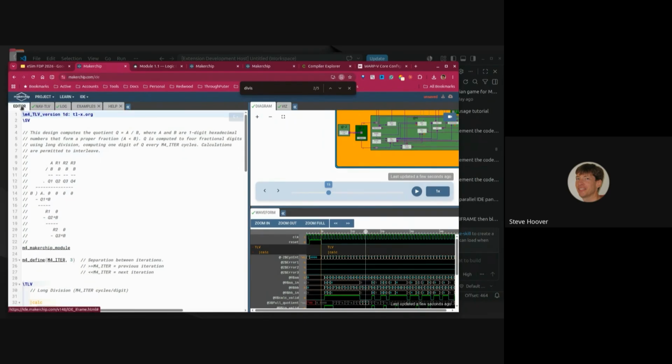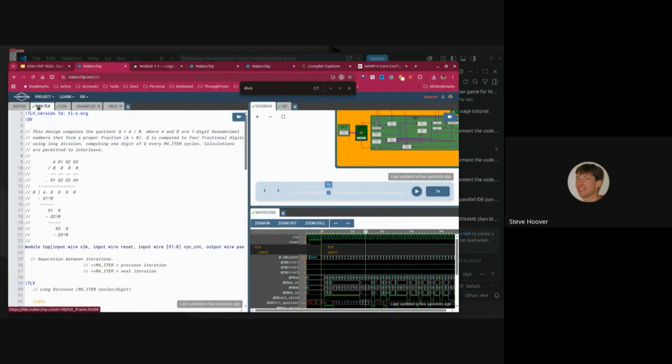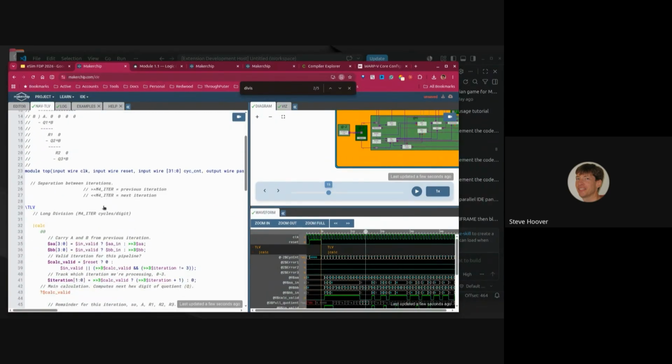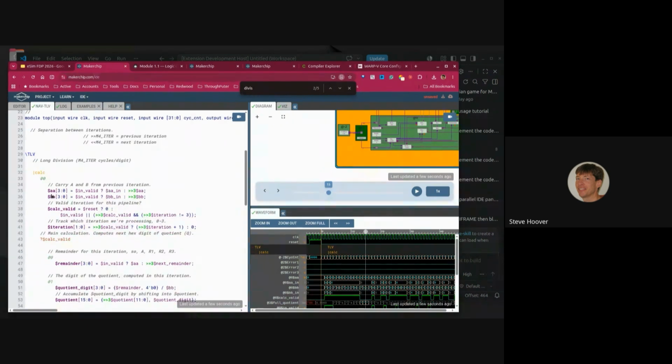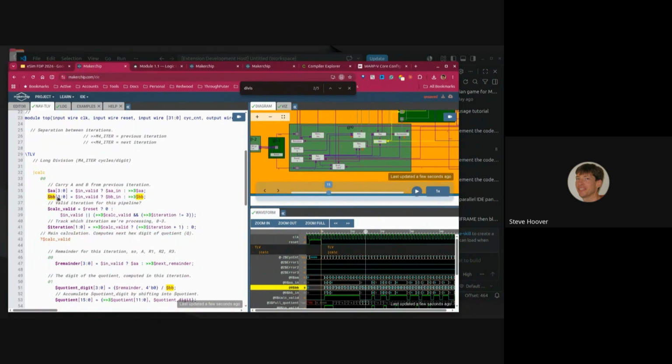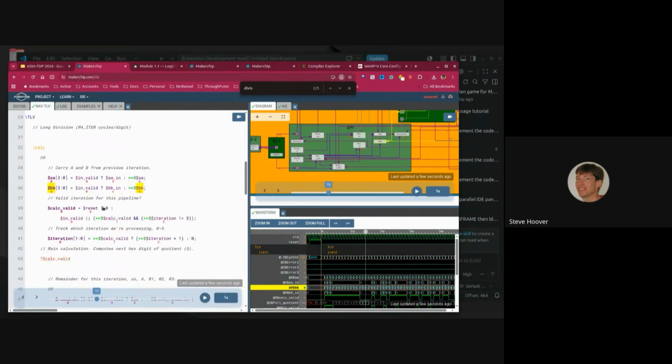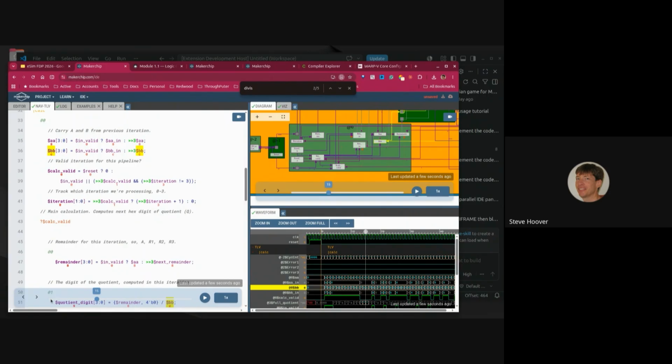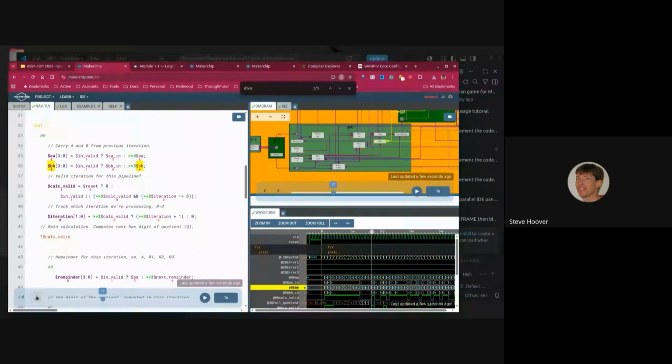So nav TLV is representing the same code that you see in the editor. It's just represented in a way that's optimized for debug, so I can interact with this view, correlate signals from the code back to the diagram. I can also go live here, so I can see the live values in simulation, and again, step the simulation to see how the values change.